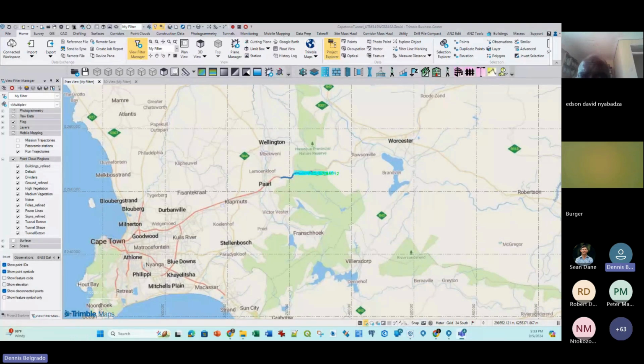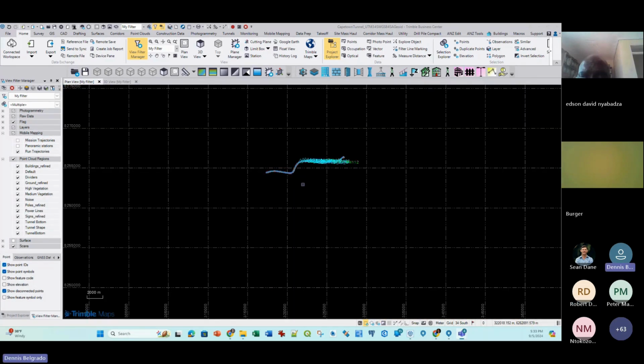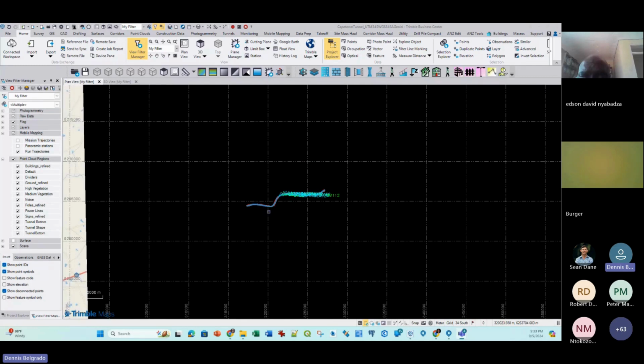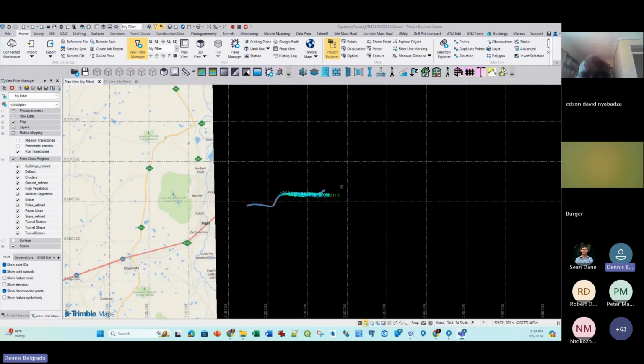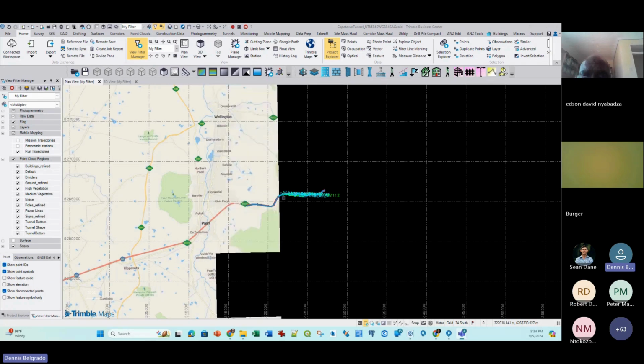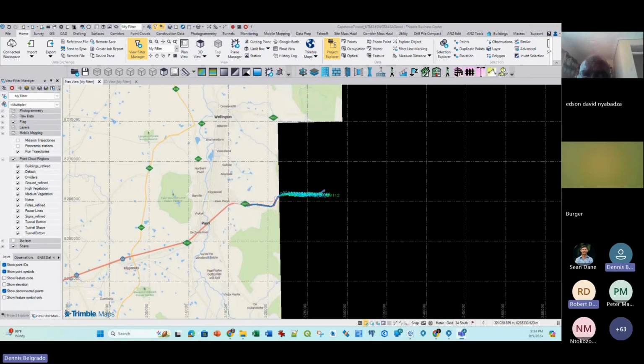In maybe 60 seconds, we can get away by using the IMU data. But in this example, we have 4 kilometers of tunnel, and there's no way that you can cross that in less than 60 seconds. So somewhere along the line, your accuracy will drift, okay?